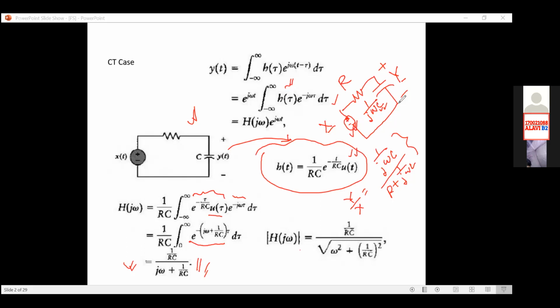Yes, sir. So if we want to proceed in this way, then you can easily examine the nature of your output by examining the magnitude of H and the phase angle of H. H will have a phase angle, say phi H. That phi H we can easily determine from this complex function. Now, if we examine in what ways your H is changing with frequency, that will tell you in which frequency range your circuit will be operating properly.